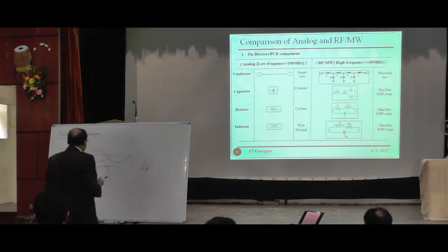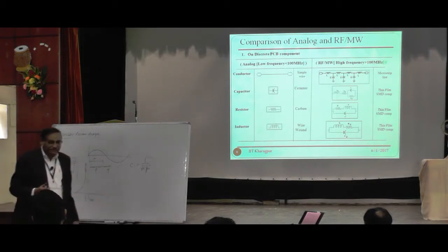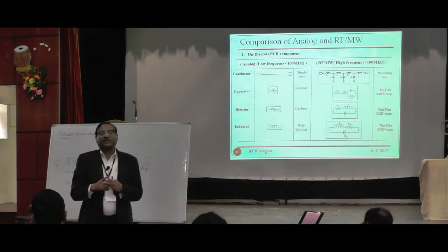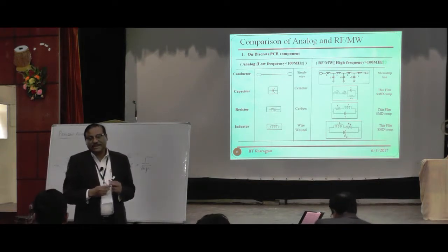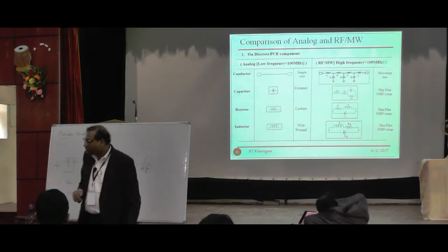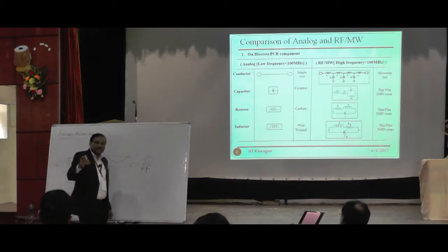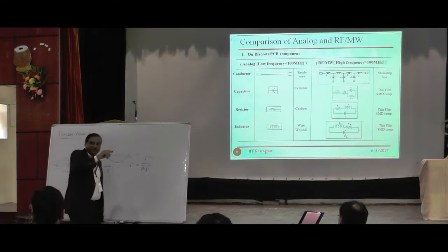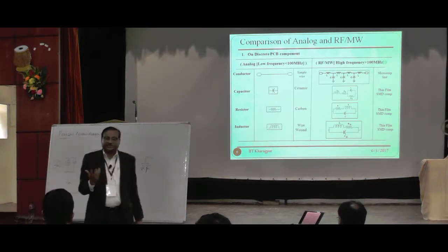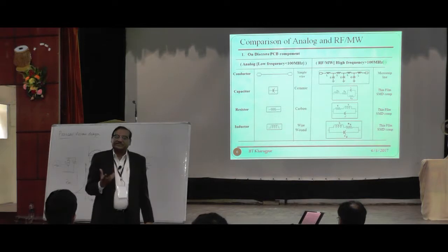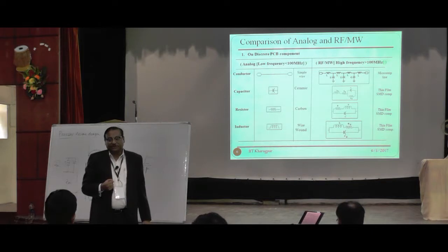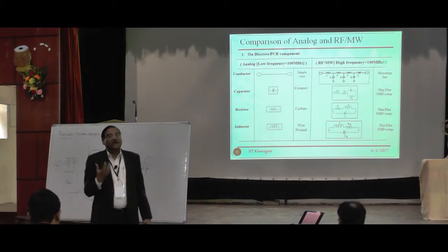Okay? How do you resolve this issue? In 65 gigahertz, first of all, the cutoff frequency of your transistors should be as high as possible. And then I go to the silicon process probably to be better for you, but just I will tell you that there is a special substrate. A normally high resistivity substrate is used to improve the cutoff frequency of the transistors. So you should have at least the cutoff frequency of transistors 10 times higher than the operating frequency of that.